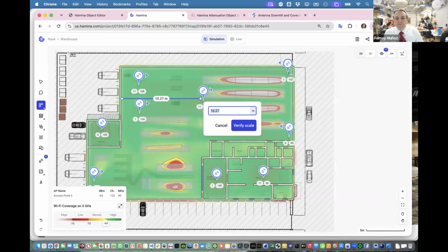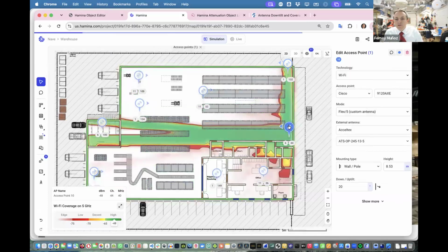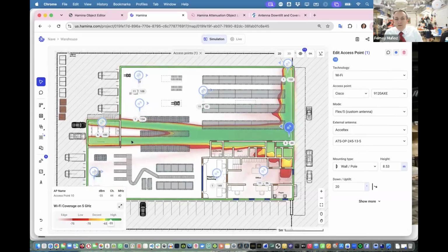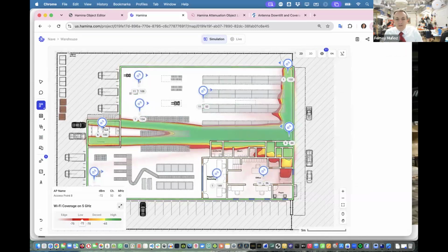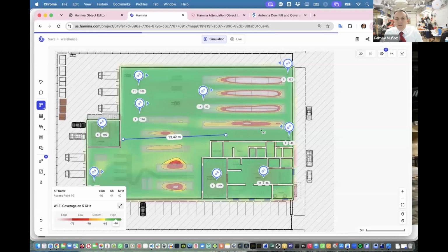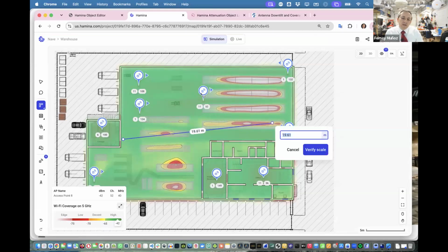But if you are now looking at this antenna and you associate with that guy and you're all the way out here, okay, then you're going to be connected 22 meters away from that guy. So that's another approach: placing this type of antennas in the middle area, not mounted sideways, but mounted all the way straight down with the right orientation, is going to provide that type of coverage. All right.